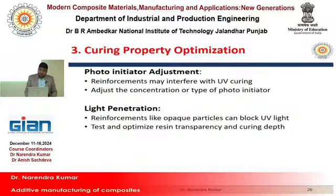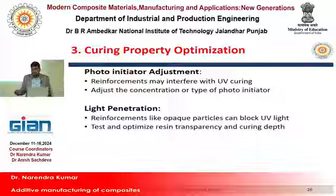Light penetration: as I told you, no heating mechanism is involved in this process. Here we are dealing with UV light, right? I mention one point: reinforcements like opaque particles can block the UV light. If they block UV light, what will happen?